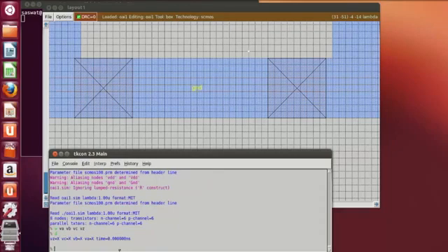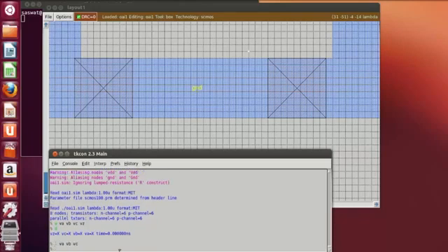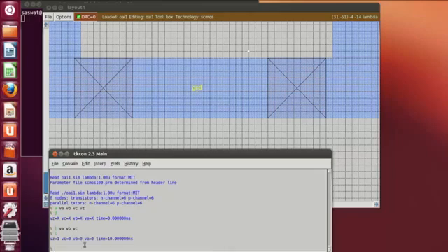Now if I type low value to VA, VB and VC, what will be the output before pressing? If these two are 0 0, then this is A, VA or VB, output will be 0, and VC, that is 0, then the total output will be 0. This is Or and Invert, then the final output will be 1. See, this is 0 0 1.